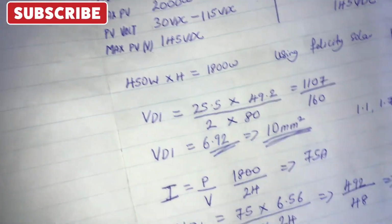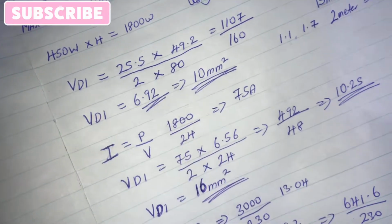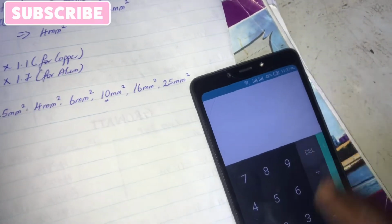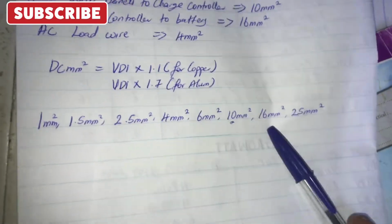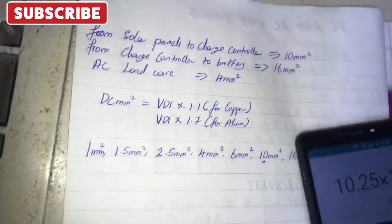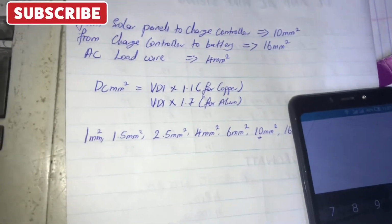Still doing the same thing for this one, we have 10.25. If you multiply 10.25 by 1.1, you have 11.2. And after 10, what we have is 16 mm. So we are still in the same place. The only difference is when you are using aluminium wire instead of copper wire.